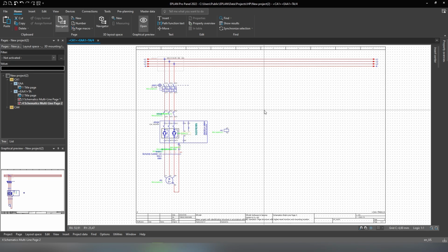But some customers like it when they can see the real item, like for example maybe a power analyzer. They can really see that power analyzer and not just see a rectangle and wonder, what's that rectangle, and now they have to check what the DT of that rectangle is, and reference in your drawing where it is located and see, oh, it's actually a power analyzer. So it's nice to see the device itself. So sometimes on the EPLAN data portal you don't find certain parts, so you have to go to the website of Siemens or Eaton or whatever, and once you go to their website you actually don't find the EDZ file.